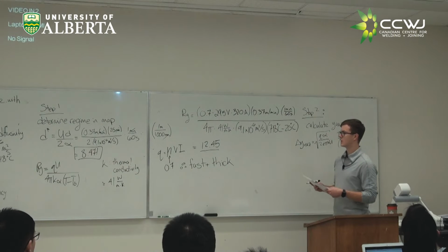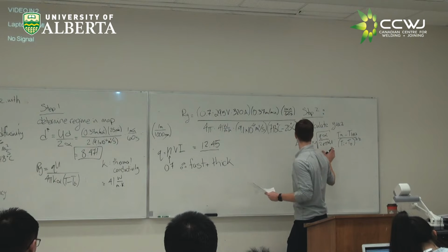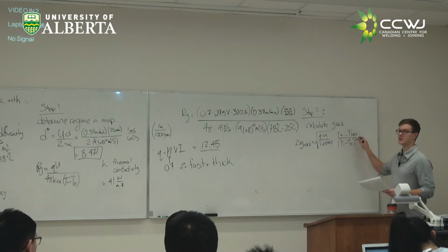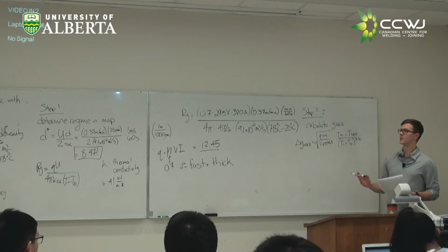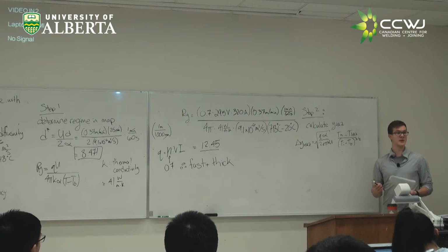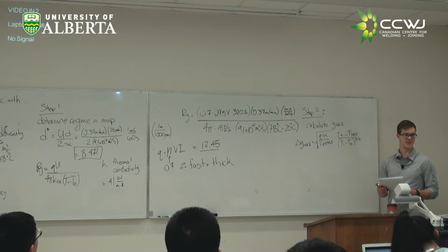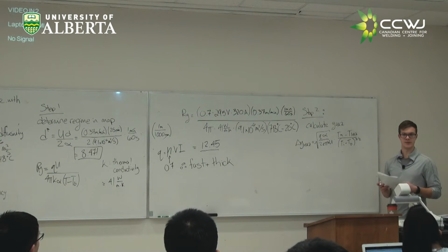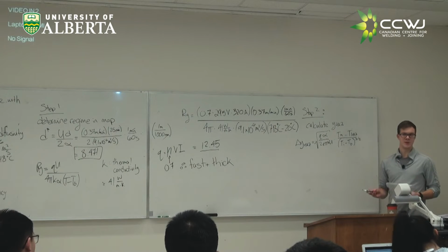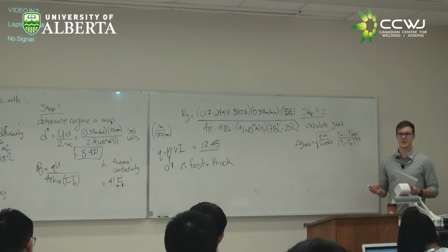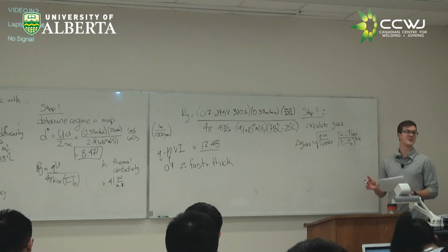So, one thing I want to clarify: when we calculate our heat affected zone, we're using the melting temperature to the heat affected zone. That's the range of temperatures we're dealing with. So we use 718 here. Probably a better temperature to use would have been somewhere in the middle, 1045, give or take. I think that's what's used in the example from the exam last year. If you're not given a temperature to use, using an intermediate temperature or melting or heat affected zone, whatever you do use, you always want to say, okay, I'm going to assume this temperature.